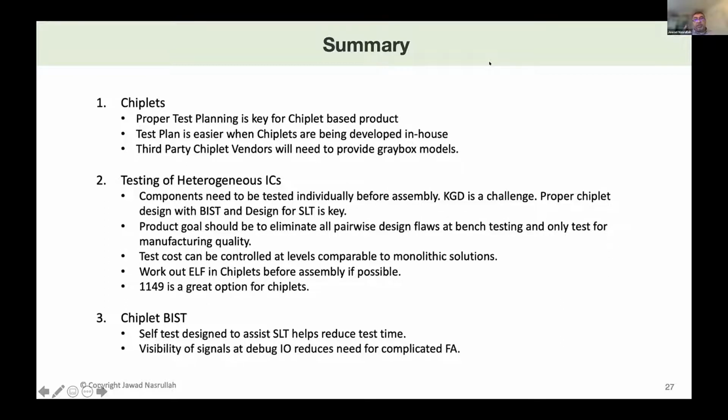Right. So an active interposer is a chip. A simple way to think about it is that it's going to have transistors. It may have advanced transistors. It may have some old ones. So you have to, number one, put scan in there for sure, right? And that active interposer has to be probed by itself before the assembly.